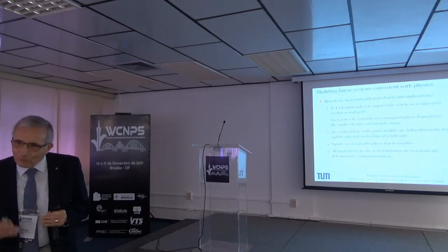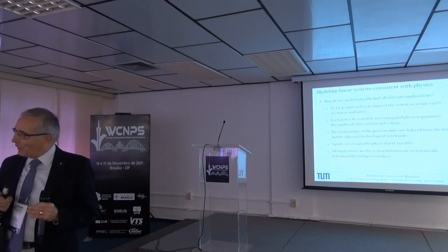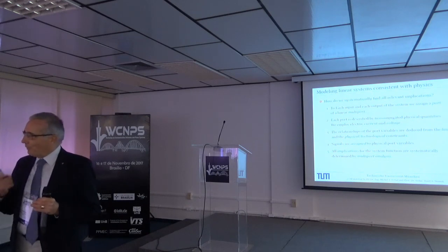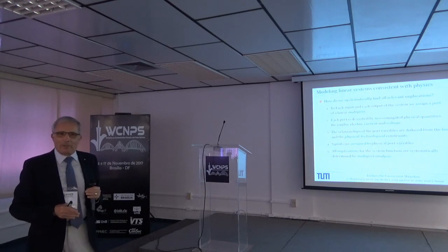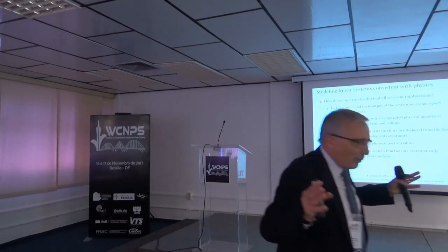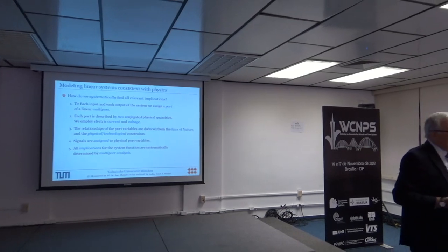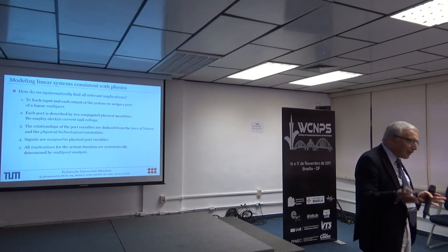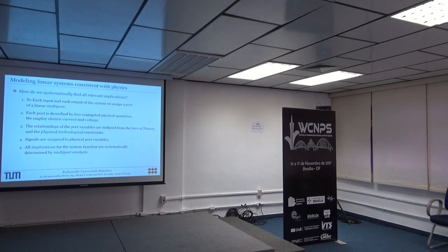And the question of what x has to do with the transmit power is a complicated question, which we have to address and solve. Otherwise, we will not have the proper transmit power. And I'm not sure how many people, with smartphones and base stations, have really measured transmit power. I doubt that has actually been done, because to do that is complicated. You have to go with a sensor antenna on a sphere around the base station, collect all the power contributions and average them out over the area of the sphere, and that is transmit power. Normally what people do is they disconnect the antenna and connect a power meter to the output of the power amplifier. In that sense, of course, mutual coupling is gone because the antenna isn't connected anymore.